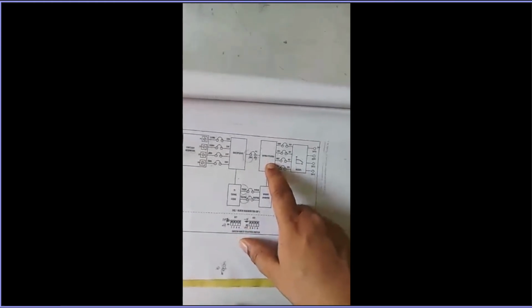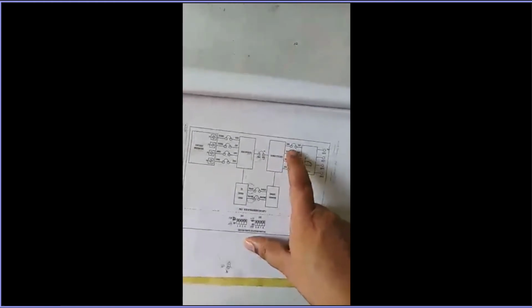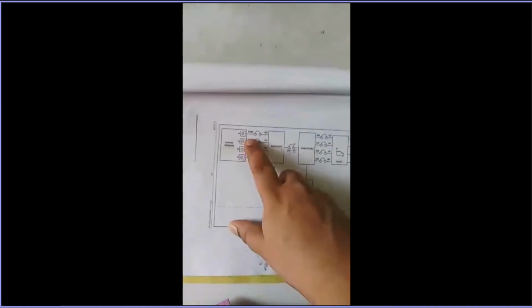The demultiplexer is capable of separating the signals again into channel number 0, 1, 2, 3. And we have the filter here. On the basis of the cutoff frequency, we have the band pass filter basically. This filter is a band pass filter, because if we use a low pass filter, then the filter that allows 500 Hertz will also allow 250 Hertz to pass.